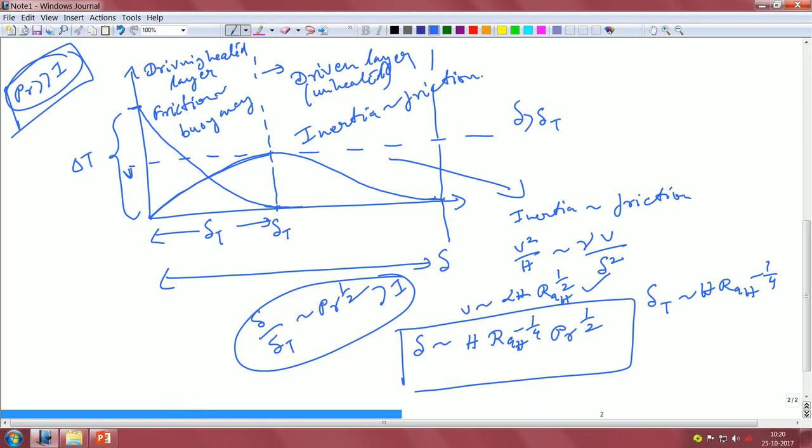In terms of temperature, the buoyancy and body force term combination is inbuilt in the momentum equation. So, it is very natural that your velocity profile is now going to be determined by a two parameter kind of a set, delta and delta T, unlike in forced convection, where it was decoupled from delta largely, unless there is some property variation that you are taking into account.